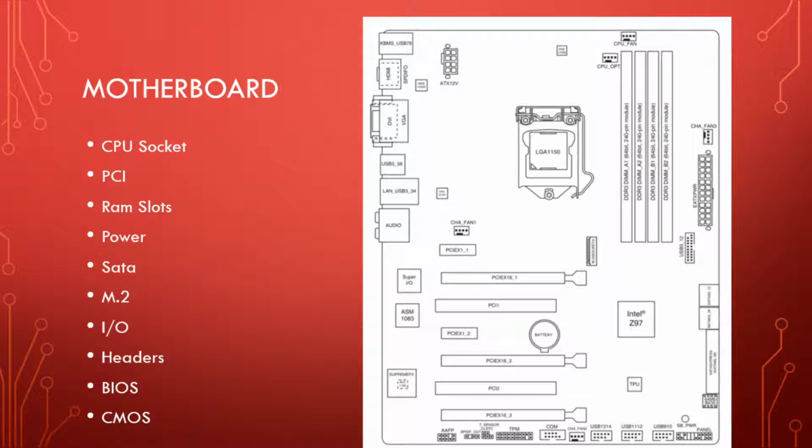Now, the benefit to that is when you've completely screwed up your computer, you can reset the CMOS by hand by taking the battery out, because there is a little coin cell battery on your motherboard. And that will reset everything, so hopefully you can still boot your computer if you screwed up overclocking or settings or something like that. So that is the benefit for that one.